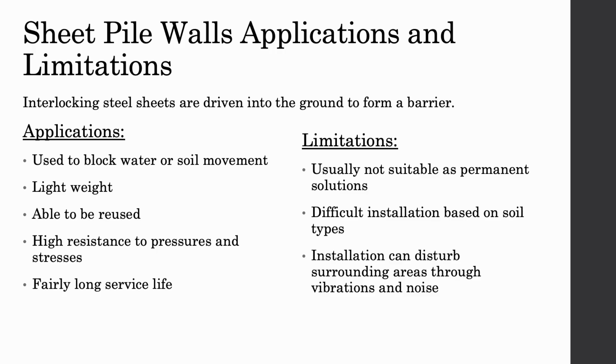Some limitations of sheet pile walls are that they are usually not suitable as permanent solutions, have difficult installation based on soil types, and installation can disturb surrounding areas through vibrations and noises.